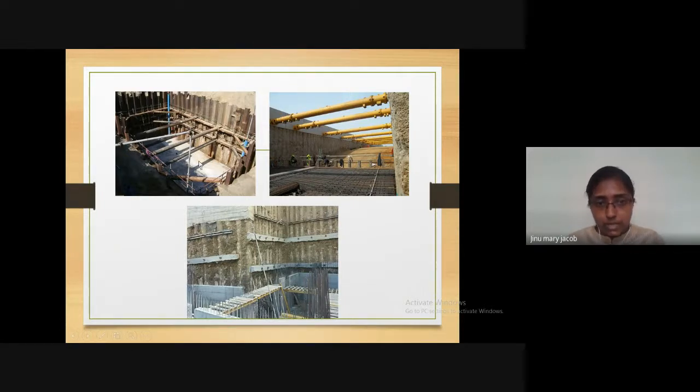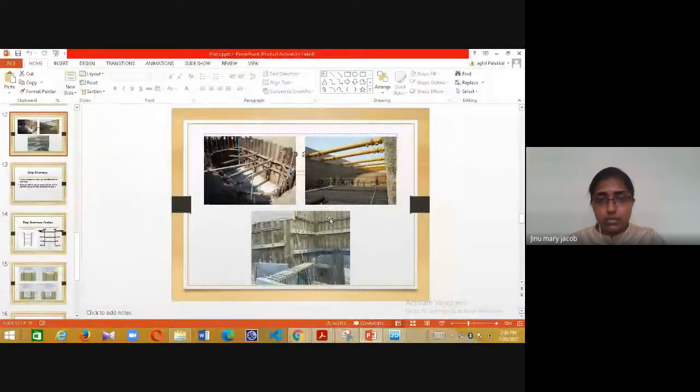So there is dewatering inside as well as outside, so that on the side of the excavation there is a water table drop. That is usually planned. Suppose it's a secant pile wall, which is more rigid and has less chance of water seepage, then we can take the water level vertically along with the pile. If there is a dewatering point outside, then we can show the lowering this way. So it is dependent.